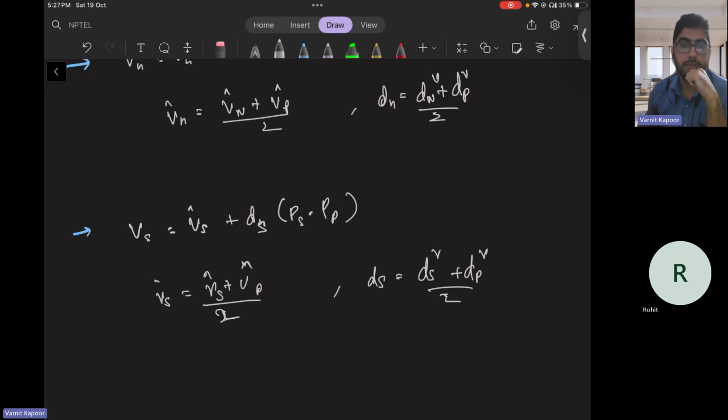Then what do we do if we use these phase velocities in the solution of the continuity equation? If we solve the discrete momentum equation, let us say for U star and P star, then the converged U star at the cell centroids, the UP star, VP star field, even if you construct the phase velocities, will not satisfy the continuity equation. That means the flow rates you would get, Fe star, west, north, south, will not satisfy the mass flow rate continuity equation for any cell, because these come from the solution of the momentum equation for guessed pressure values.